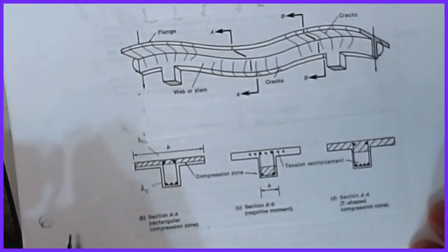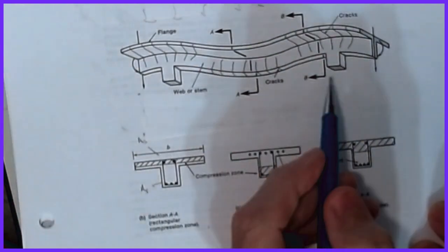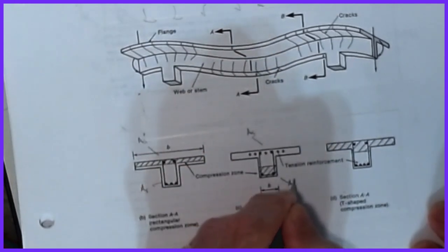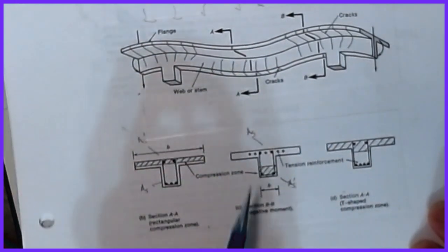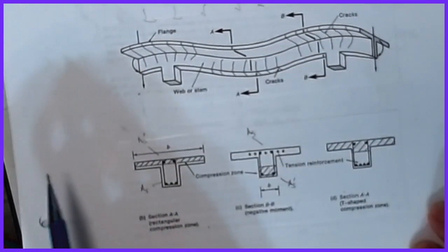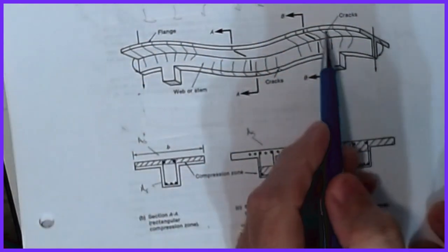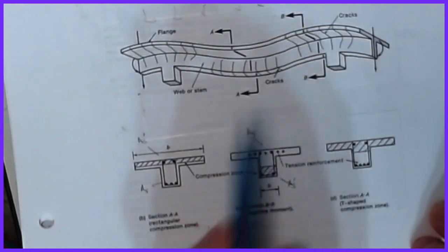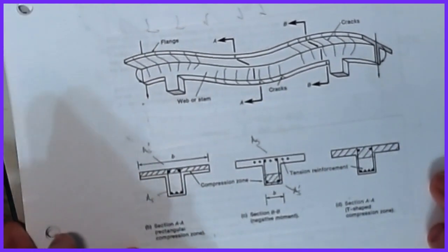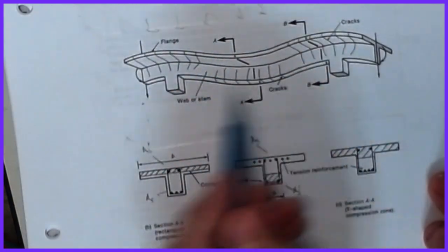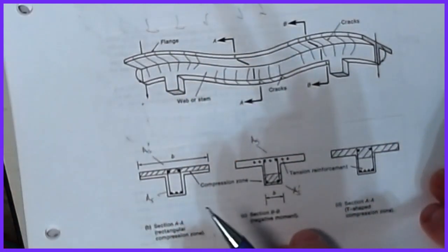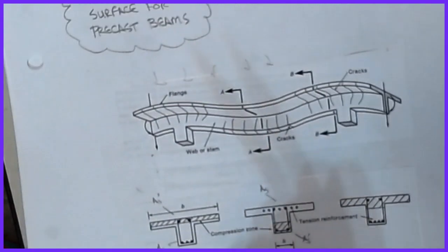And then when I look at section B, which is now the one over at the support, it flips. This now becomes A_s, and this becomes A_s prime. Okay, and so you would have to come up with reinforcing patterns that will solve both of those problems, for both the maximum positive moment and the maximum negative moment. Okay, so that's why we need these envelopes, and we've got to be able to know what the largest of the two is for the beam. And this is a major, major issue in continuous structures. And so I want to take care of that.